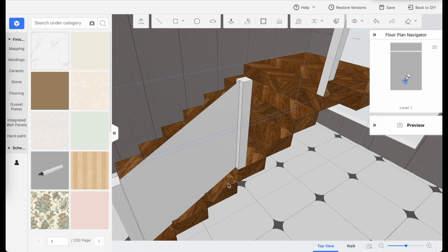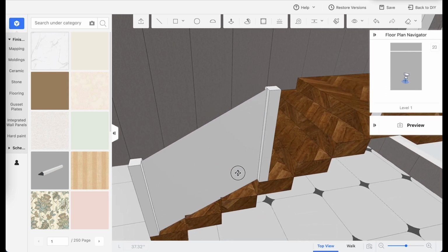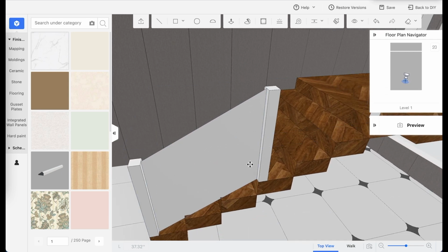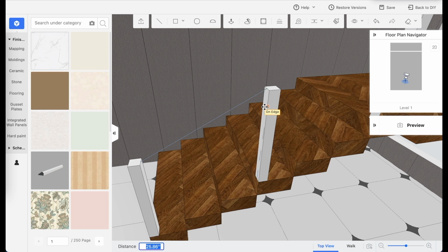You can see the surface has been created. What's more is, if you click on the edge of the surface, you have an option to move it up. Usually I move it up, making sure you're snapping to the vertical surface. Did you see the dash line turn a light blue color? That means you're on the right track.